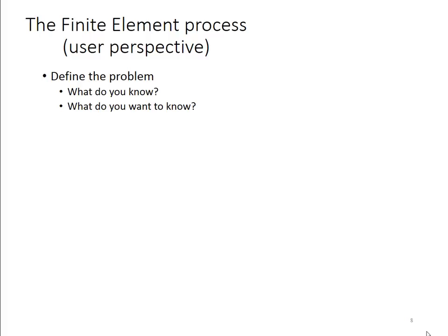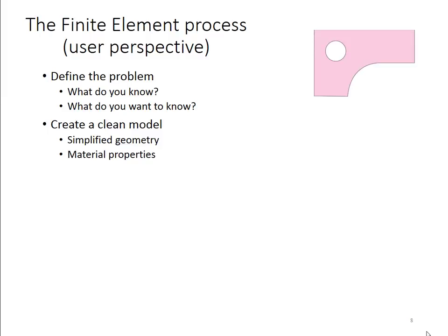Let's dive into the finite element process from the user perspective. What do you as the user experience when you are running FEA? So first off, as the user, you need to figure out what you know and what you don't know. This is how you solve any problem. So it's no different with FEA. Define the problem up front. Then create a clean model.